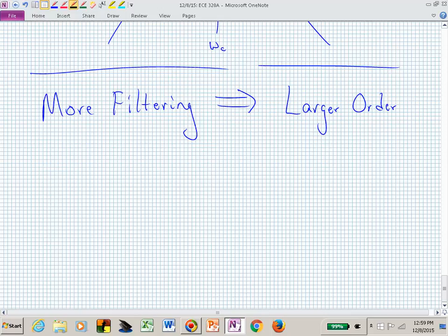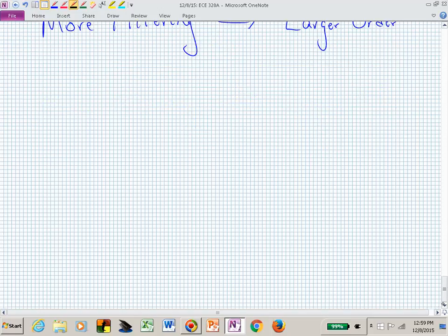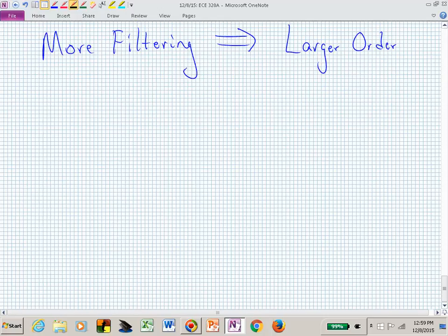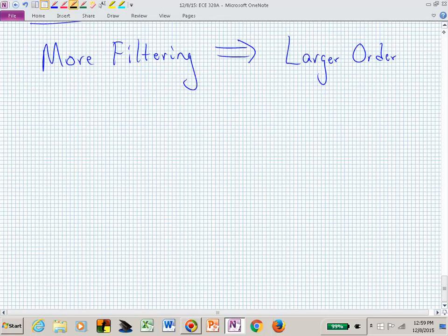Now you're attenuating frequencies from 0 to 10, and the bandwidth of that filter is from 10 hertz all the way out to infinity. But they probably would specify that as the cutoff of that high pass filter. And then you're talking about where you reach this break between where you're largest and where you're coming up from.